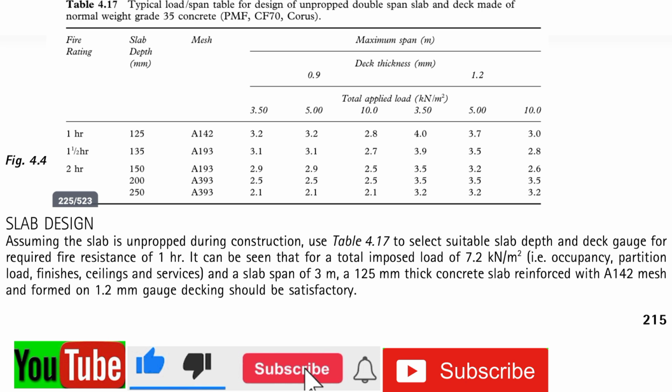It can be seen that for a total imposed load of 7.2 kilonewton per square meter, that is occupancy, partition load, finishes, ceilings, and services, and a slab span of 3 meters, a 125 millimeters thick concrete slab reinforced with A142 mesh and formed on 1.2 millimeters gauge decking should be satisfactory.